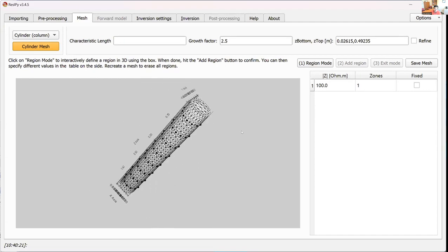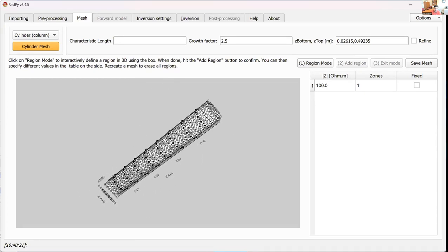So I think it's actually this way, because if you define your surface at the top of the electrodes and your bottom at the very bottom of the electrodes, for some weird reason the mesh becomes hollow. If you see a hollow mesh, or you see a fully black side to the mesh, this means that your mesh is empty and it's not going to work out. So you should not invert that data.